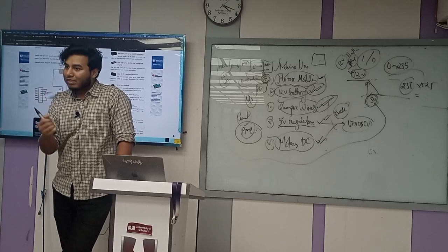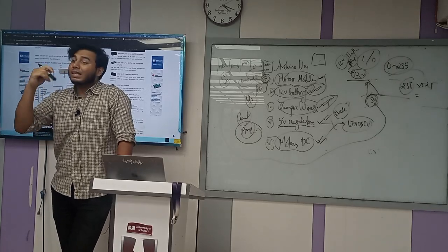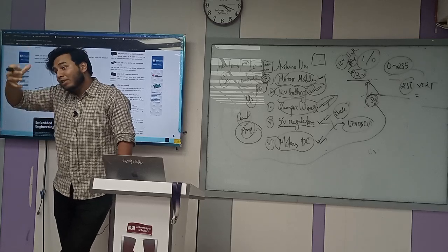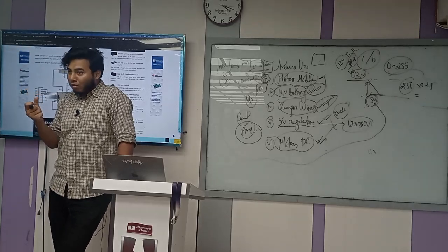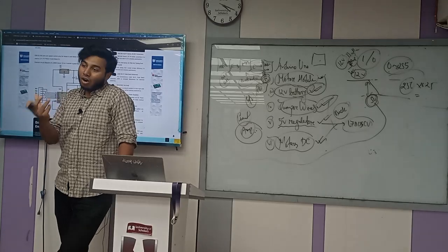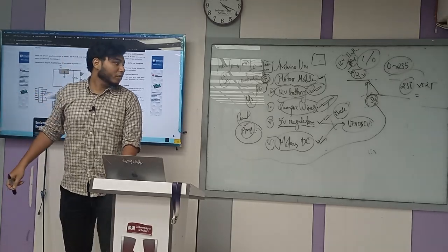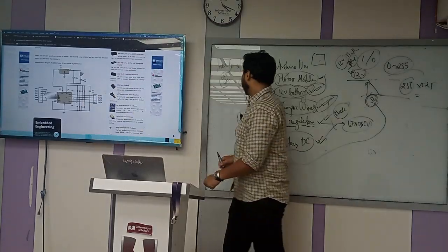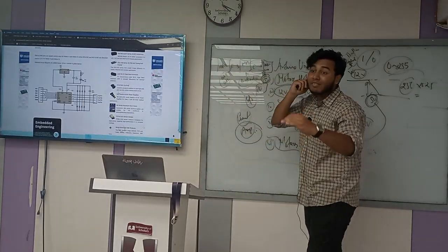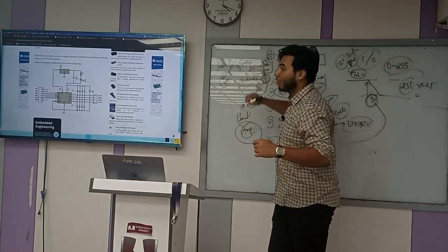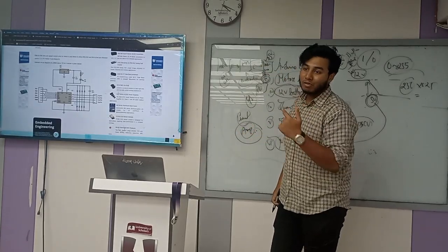Whenever we use this, the voltage will be dropped, and that dropped voltage, 7 volt, will be considered as heat, and the heatsink will consume that portion as hot air or release it to the environment. Okay, that's how it works. And whenever you need to use this, because you have a set range of input, it has a requirement of 5 volt, and you can use over the 12 volt.